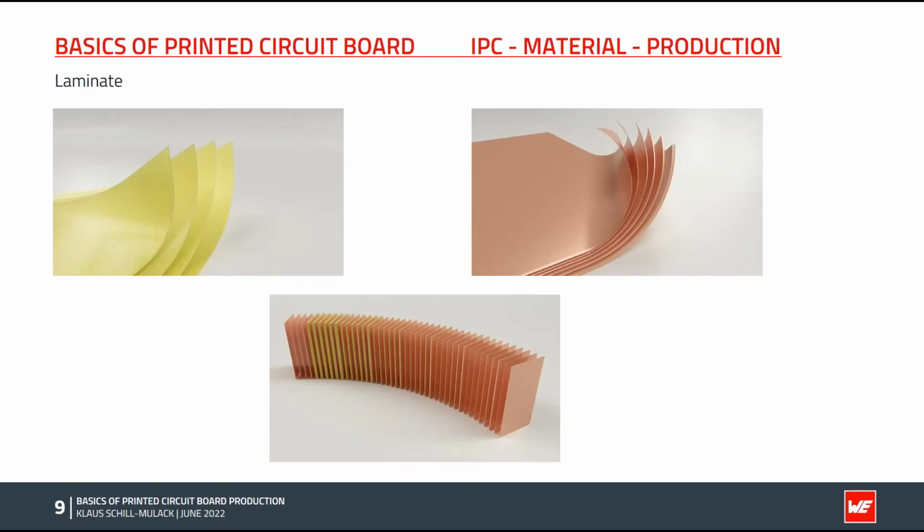So now we will come to the laminate itself. This means copper, prepreg, and the core material, which are the 3 basic materials. Prepreg derives from previously impregnated. So prepreg is the dielectric material, of course, made by impregnating fiberglass fabrics with special formulated resin. The resin has specific material, electrical, thermal, and physical properties, which makes it, I would say, the main material for electronics.